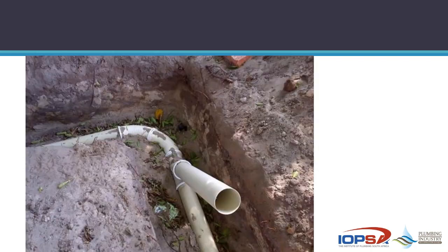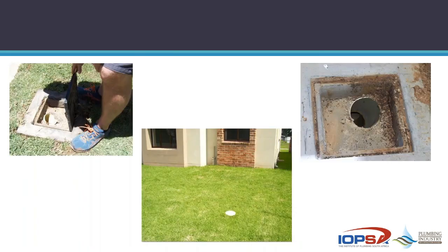And then one of the ones that I see quite regularly, I don't know how they got to this, but same thing applies. Y junction in here, rodding eye out in the straight, that gives you access down that line. Access from this line would have been from the other rodding eye. So instead of going through 1, 2, 3 bends, could have gone through 1. And this is something that the maintenance guys come across regularly.